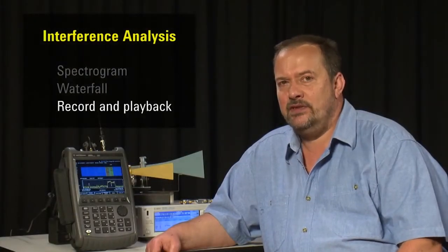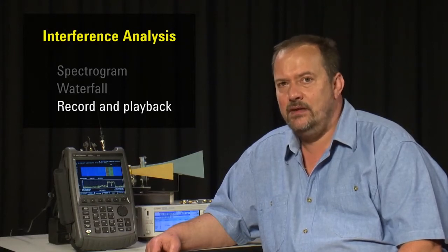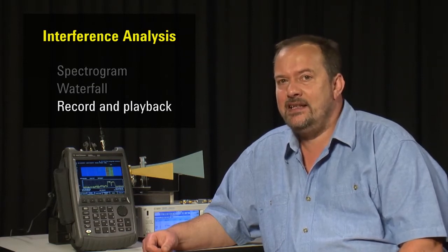The spectrogram and waterfall displays are perfect if we want to sit in front of the FieldFox and visually identify signals of interest. But what if we want to leave the analyzer monitoring the spectrum over a longer period of time, perhaps overnight or over a weekend? Well, that's where we can use the extremely sophisticated record and playback capabilities of the FieldFox. Without the need for a PC, we can tell the FieldFox to record the RF spectrum over a predefined interval with a user-defined capture interval, and each trace is time and date stamped with a GPS position and elevation as well. Ideal if we want to perform spectrum recording while mobile and record our position.